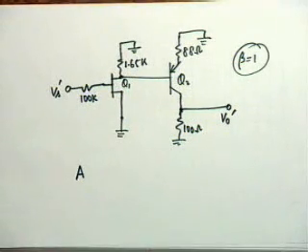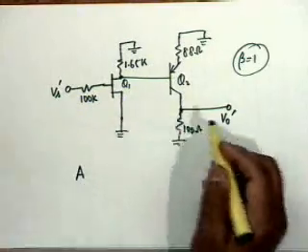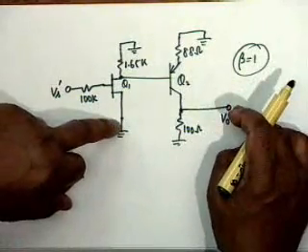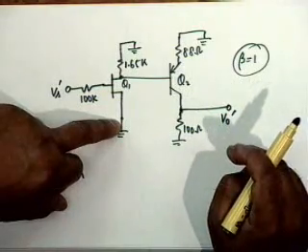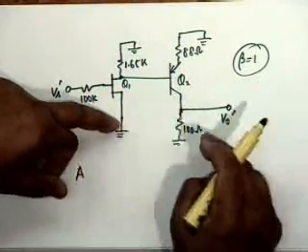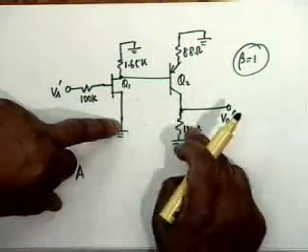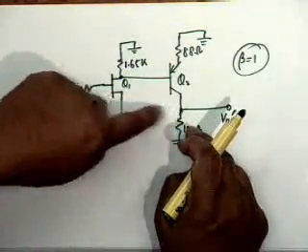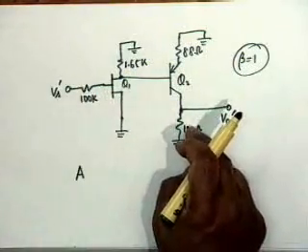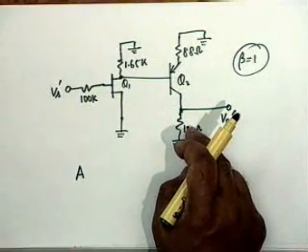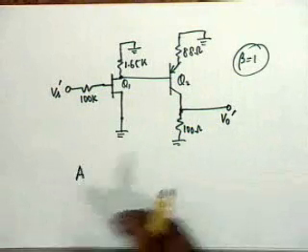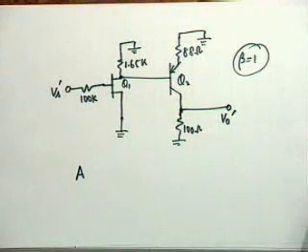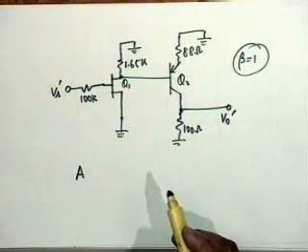Please explain why RL was grounded. Why RL was grounded? Because the output is a shunt connection. Shunt means short. Shunt has to be shorted, and therefore RL was shorted for this. RL was open for this. Input connection is series, so it was open. It's a series shunt. Okay. Now I want you to calculate the gain by inspection.